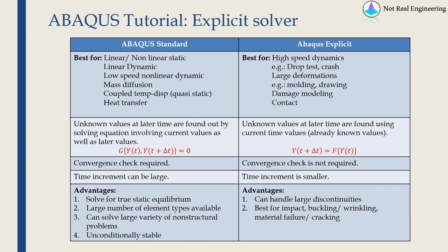Abaqus has two solvers, one is Abaqus Standard and one is Abaqus Explicit. Most of the time when we start learning Abaqus, we always start with Standard. But later on at some point, you will feel the need to use the Explicit solver. So what's the difference? First of all, Abaqus Standard is best for linear or non-linear static analysis.